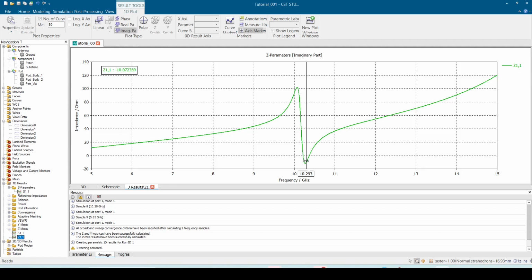So ideally, if things are ideal without this perturbation of the via or something, the crossing happens around this frequency, and this point should be down here at 0. But this means that the impedance seen is not purely real at this frequency, and sometimes we cannot really couple the low reactive part with the real part at the same moment.